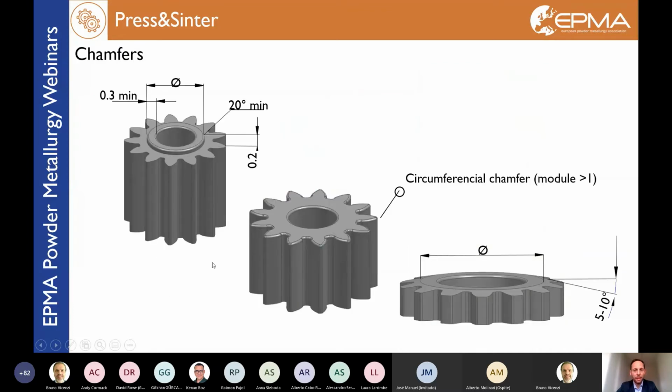So you can adopt a few tricks, let's say, especially on gears here shown. You can move the burr down from the functional plane. Let's say for gear, this would be the bearing or the actual bearing functional face, and this is a fixed step on the upper punch, and I have the burr here lower than the functional plane, and I don't need to deburr.